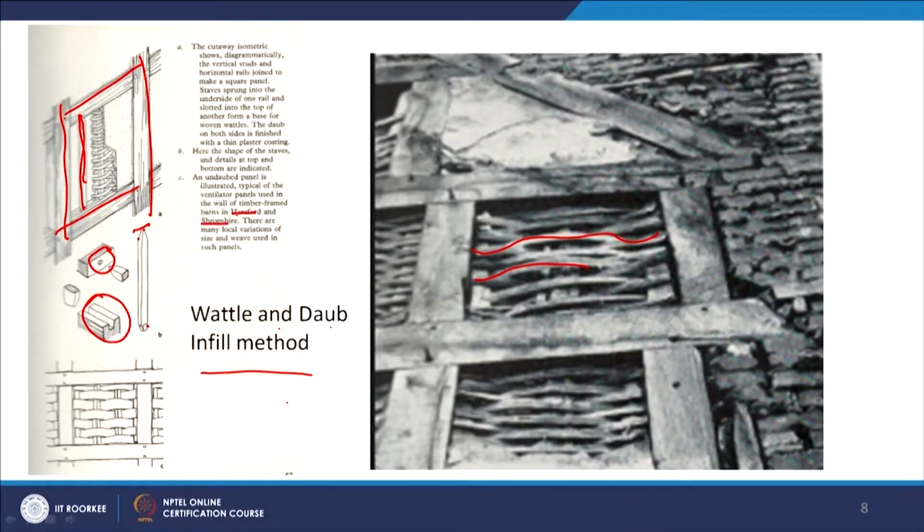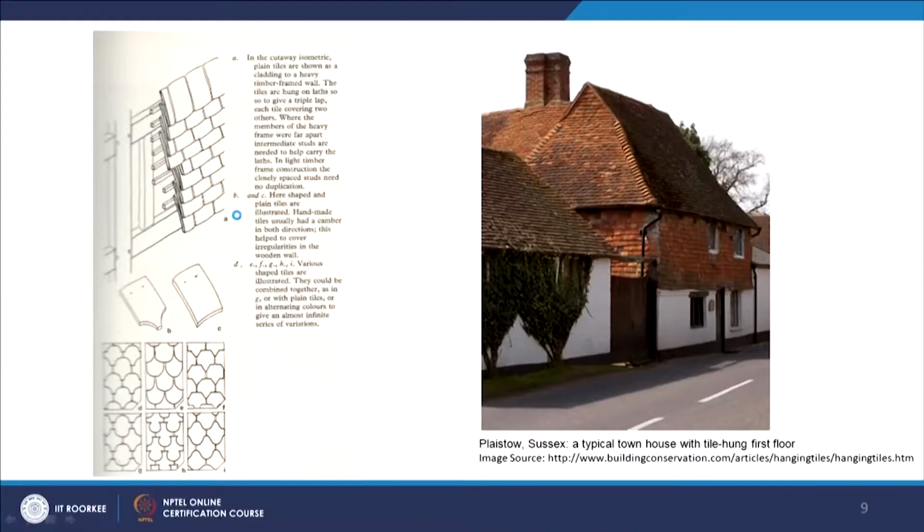and this you can frequently observe in Hereford and Shropshire, with many local variations in the size of the panels they are using. Another one, which is quite a common technique, especially with tiles, is the handmade tiles. So you can see the same frames, with small battens going in the horizontal direction, and what you see here is the overlapping of the handmade tiles.